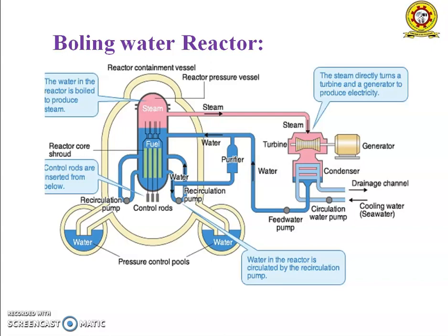The capital cost is lower as the reactor vessel is designed to take low stresses, as the pressure in the vessel is lower than in the pressurized water reactor. The requirements for heat exchangers, pumps and auxiliary equipment are reduced or eliminated, and this results in a gain in thermal efficiency, which reduces the cost. The reactor is capable of meeting fluctuations in the load requirements.